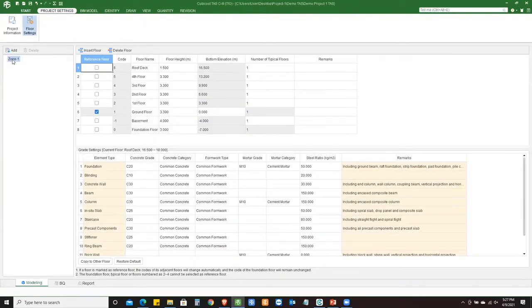you have different zones, which is basically block A, block B, different buildings maybe in your project, or different zones, A, B, C, D, and 1, 2, 3, 4, and so on. And then for each one of these zones, you have particular levels. So you can have, let's say, basement, a foundation, and a ground floor, and then you can start creating different floors. This floor setting is set up initially when we initiate a project. So we start a project. The first thing that we do is set up the elevation of the entire project. So different levels are being generated here.